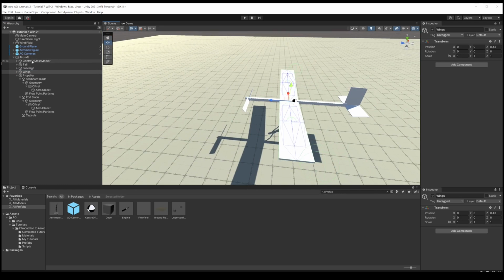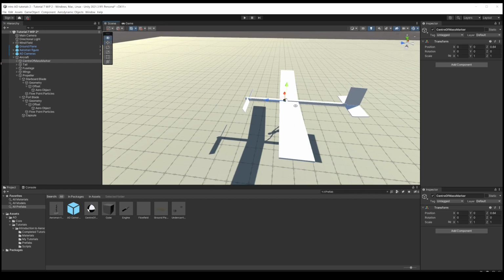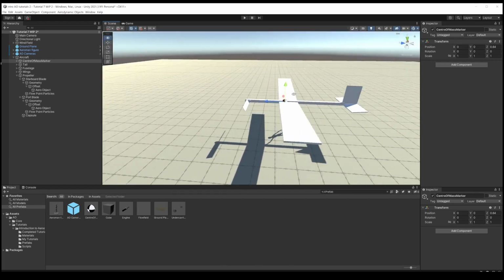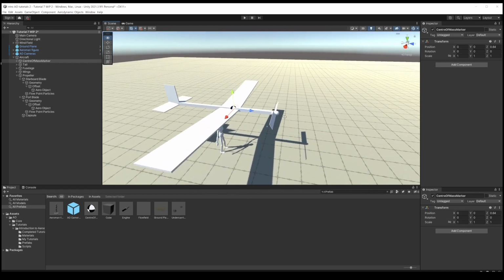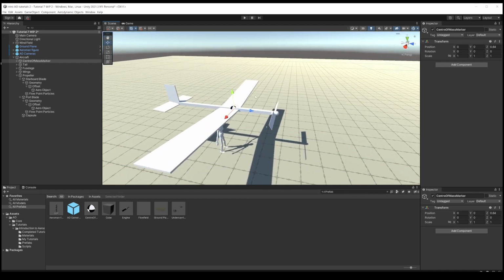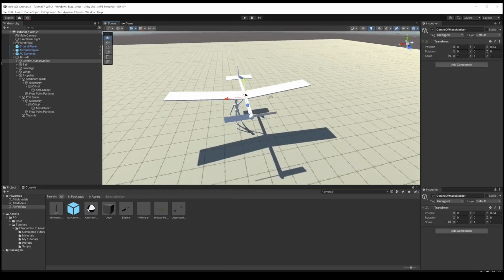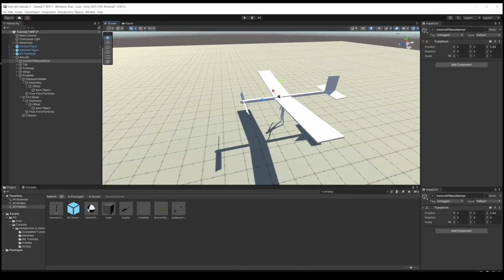And I'm also going to move the centre of gravity forward, because I know for stability reasons it needs to be between sort of 1/4 and 1/2 back from the leading edge. And this is where the magic happens with aerodynamic objects. We're just moving things around, but the code underneath just says fine. That's where our wing is, and it does its calculation, and we're all good.